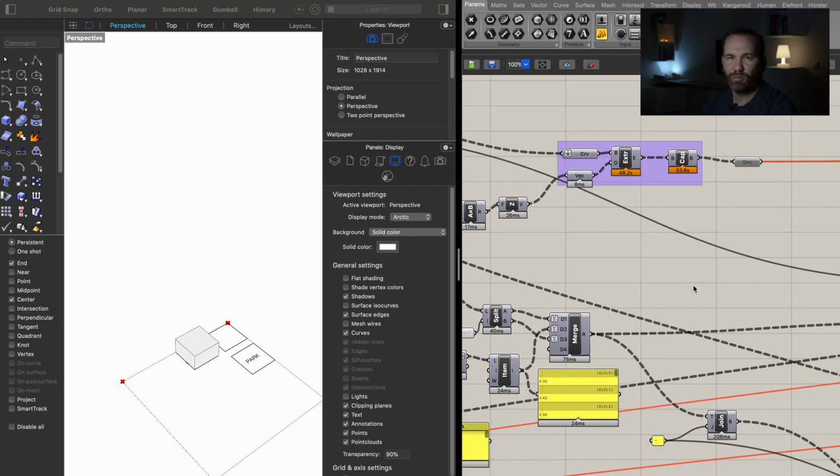One way to speed this up is to remove all the empty branches from the tree of the heights. So we will do that first. And the second way to speed this up will be to start using meshes for the 3D model of the towers instead of the extrusion and capping, which is NURBS modeling, a bit slower. Meshes actually make sense because it will also avoid the converting to meshes we have to do when we're calculating the shadow, so it will speed up the model altogether.